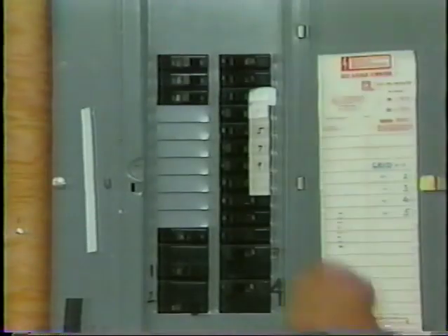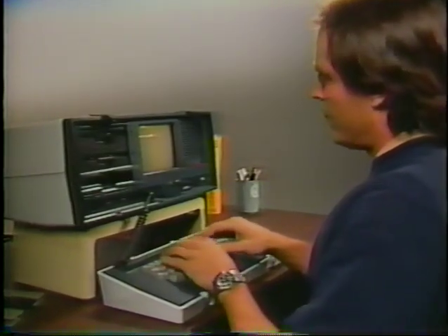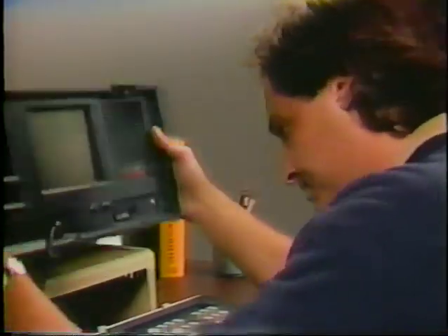In fact, the sole purpose of a circuit panel is to limit the rate of electricity in a building. If the wires begin to heat up from too much current, the breaker trips. Even the breaker itself operates by heat. As the rate of electric current increases, a bimetallic strip inside the breaker heats up and bends. The higher the rate, the more heat and the more bending. Finally, it reaches a point where the flow of electricity is cut off altogether. Even when a device has been designed with wires properly sized to handle the current, some heat is still generated, and it can build up over time and still cause problems.